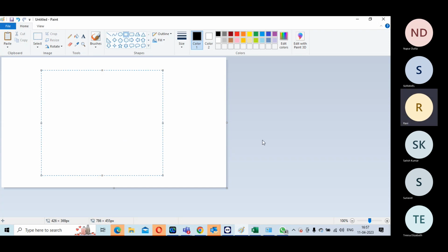Let me say over here, this area is 100% utilized. There's no space for hold fixing or setup fixing, but there are setup and hold violations here. Let's assume, for example, you have a setup violation. We can see the data path, and we can downsize some cells. Which cells will you downsize? In the data path where you have the violation.